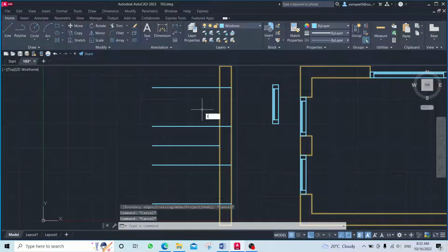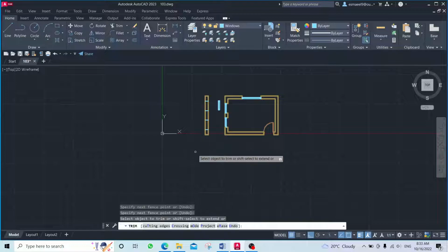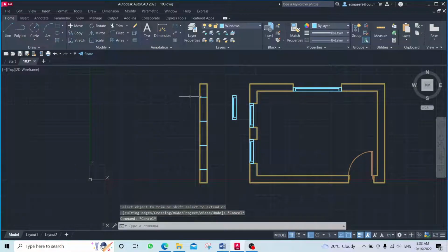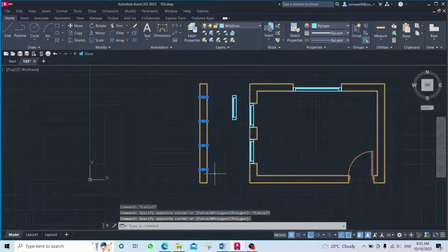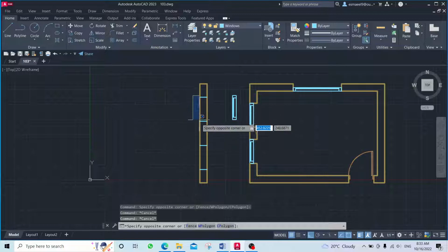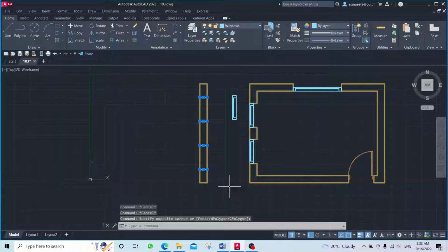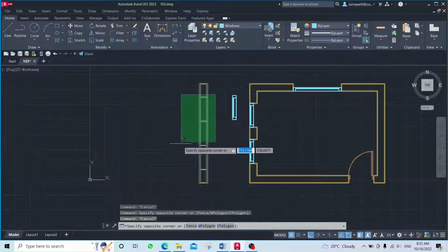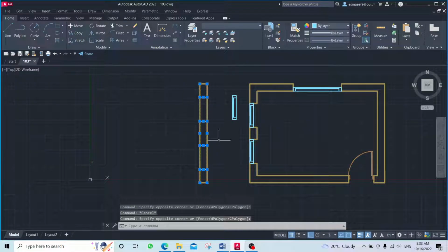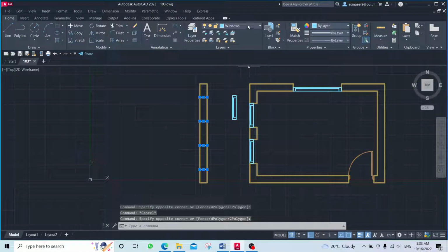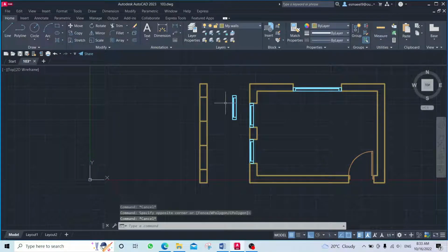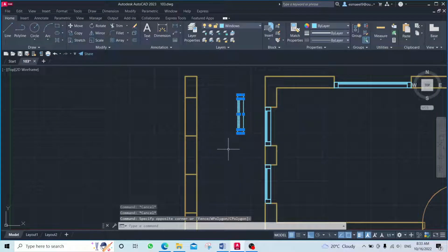What I'm gonna do: TR, double click, delete all, and now select. Can you see when I'm selecting again the interior, only the interior lines? I selected it using the blue rectangle. It's the same in this case actually if you select all, but what I actually want now is only the interior one. So I will select them, make them walls, and now select your window.